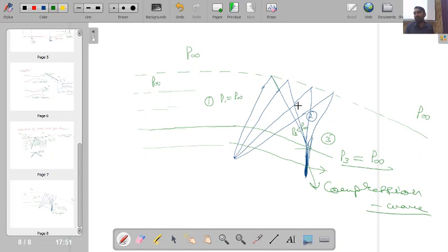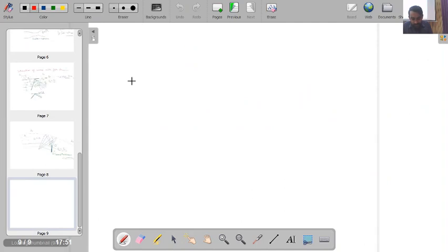Okay. Now let's see how this alters our phenomenon, or how it gives a particular type of flow structure on the downstream of the nozzle when we have this type of occurrence of the waves. Typically what I can do is consider a nozzle, and say this is nothing but an over expansion nozzle. Okay, so if I have an over expansion nozzle, what will be happening?